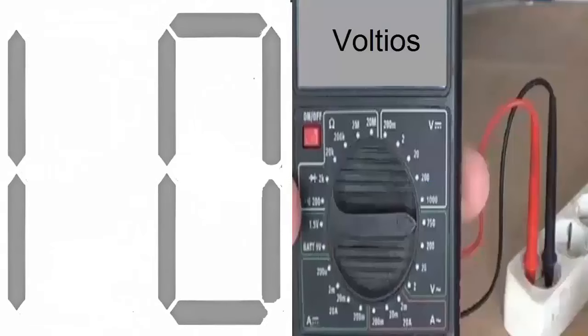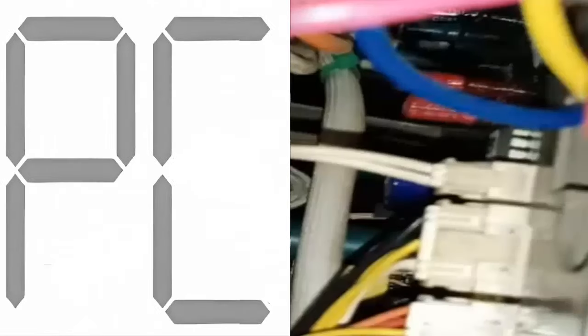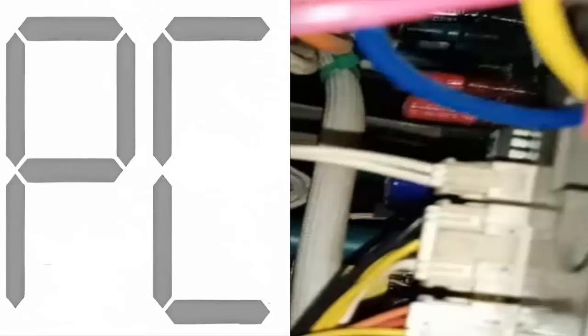C. The second step is to check the firmness of the connections and the condition of the power cables. Loose connections or damaged cables can create electrical resistance, which can affect the supply voltage value.